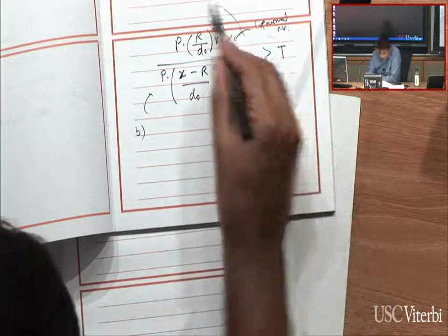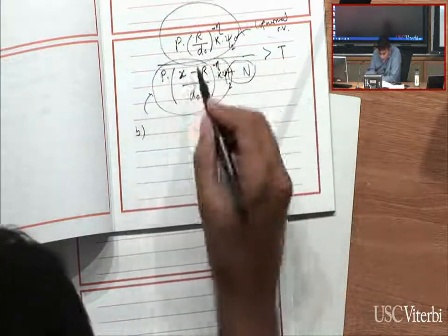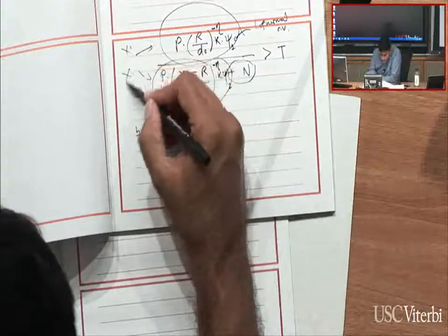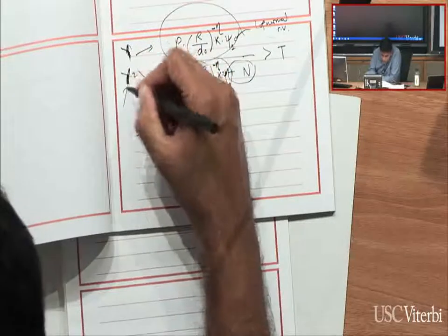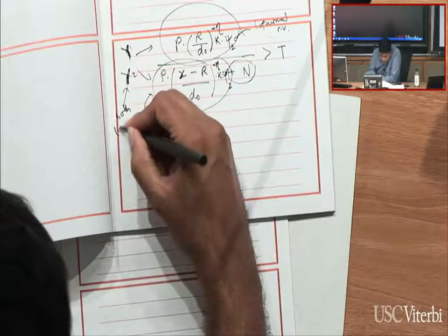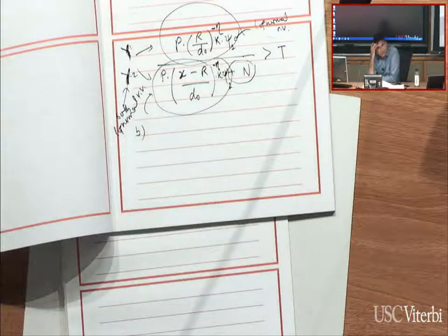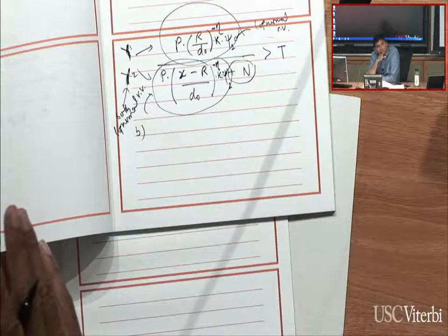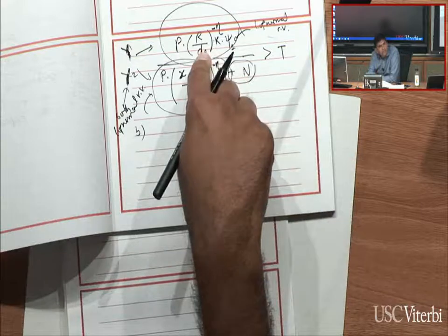So this whole thing and this whole thing, these are both, let's call them y1 and y2, log normal variables. Not only is the fading a log normal variable, the total received power is also log normal. It's just shifted by this amount in the dB scale.